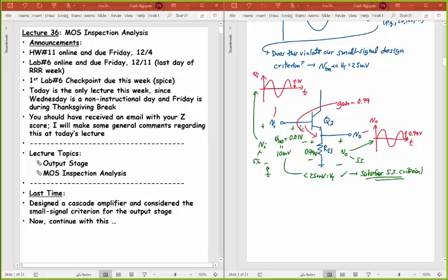I was talking about how the signal across VBE could be very small, but the signal going across VCE here, the small signal VCE, may not really be a small signal anymore. So how can we still use small signal analysis when VCE is moving so much? Well, what you need to remember is that the IV characteristic that we're worried about here is this one.